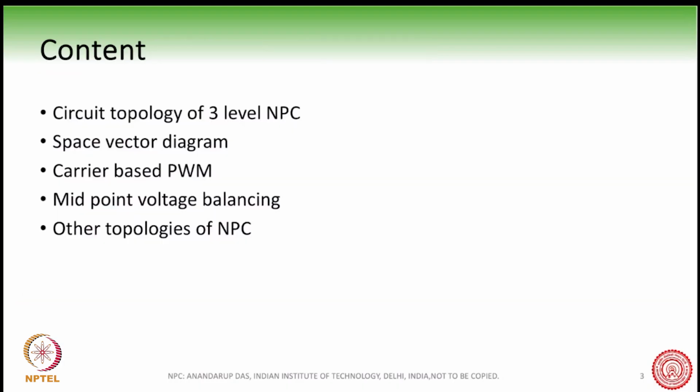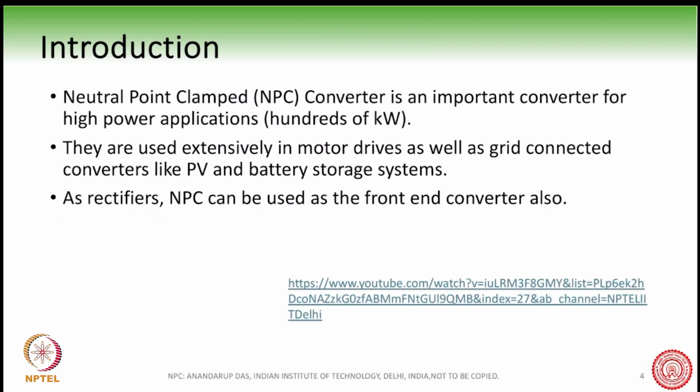With regard to the neutral point clamped converter, we will talk about the circuit topology, the space vector diagram, a little bit of carrier based PWM, and midpoint voltage balancing and other topologies. The neutral point clamped converter is an important converter for high power and three phase applications.